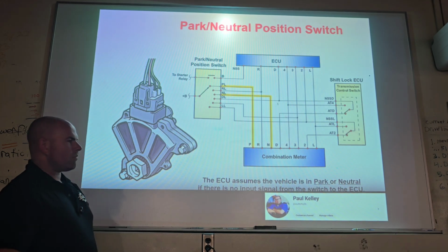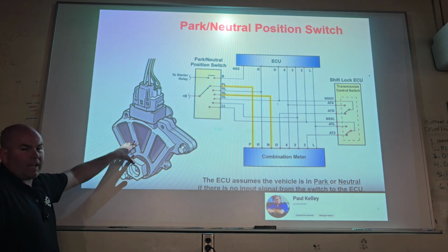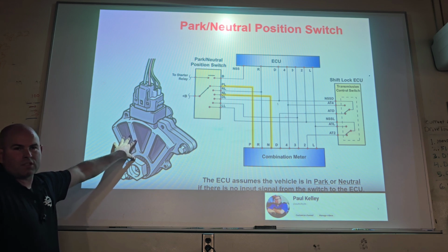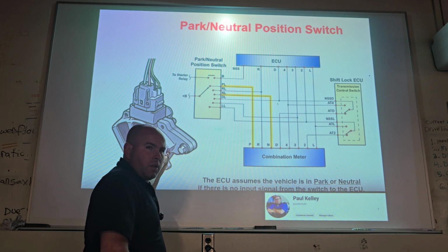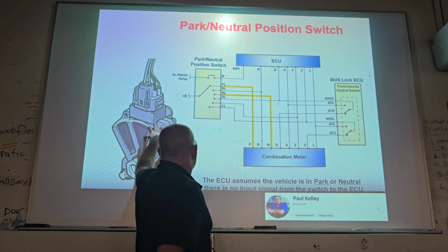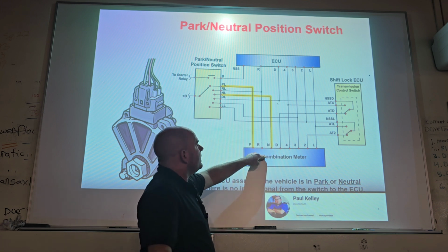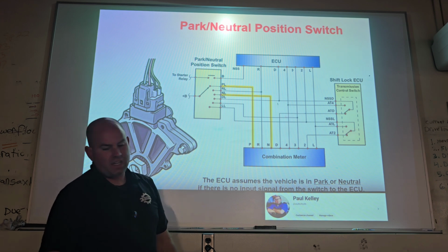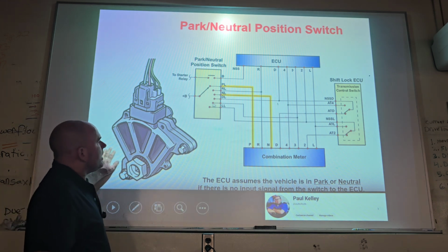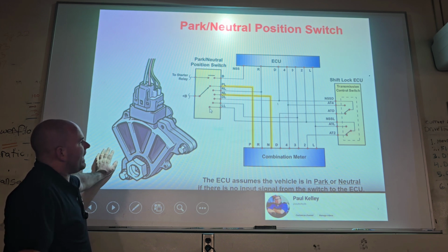Similar with the neutral safety. We covered this already in the range switch, but the neutral safety switch a lot of times will come in as a no crank, no start, but we may very well be looking at the transmission, looking at this adjustment, and as you can see, park and neutral are needed to allow that actual starter. Cool? But if you also look right here, there's a whole bunch of switches. Cool? And the ECU needs to get a reference of each one of those.